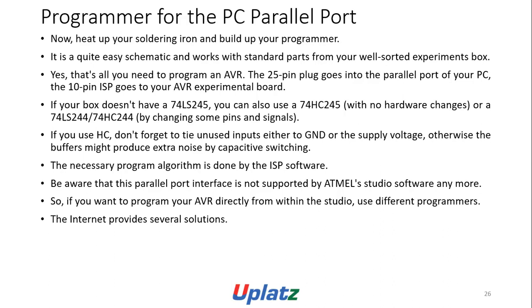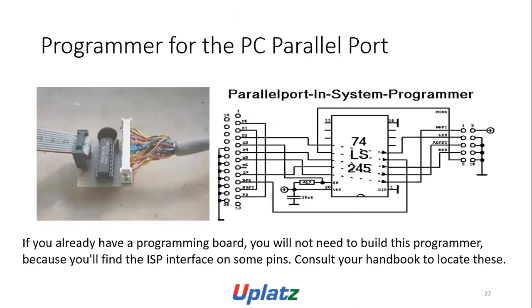If you use CMOS, don't forget to tie unused inputs either to ground or to the supply voltage, otherwise the buffers might produce extra noise by capacitive switching. The necessary program algorithm is done by the ISP software. Be aware that this parallel port interface is not supported by Atmel Studio software anymore. So if you want to program your AVR directly from within the studio, use different programmers. The internet provides several solutions. If you already have a programming board, you will not need to build this programmer because you will find the ISP interface on it. Consult your handbook to locate this.